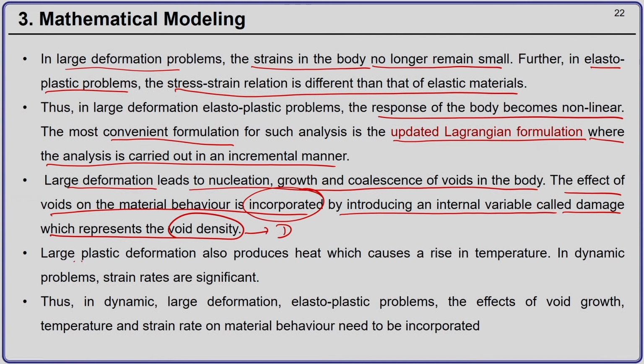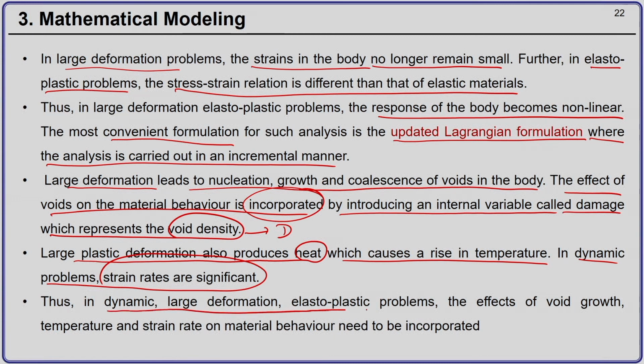And large plastic deformation also produces heat, which causes a rise in temperature, and in dynamic problems the effect of strain rates is also very significant. Thus, in dynamic large deformation elastoplastic problem, the effect of void growth, temperature and strain rate on the material behavior needs to be incorporated, and this is what we are going to do next.